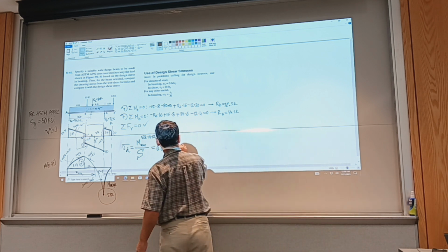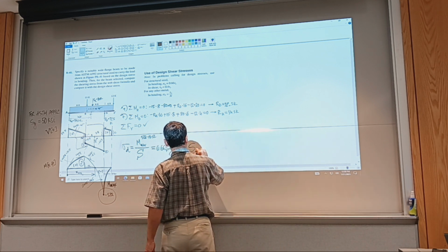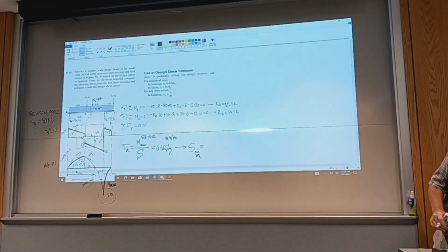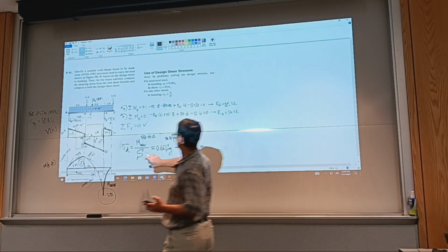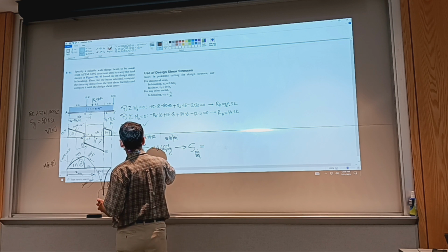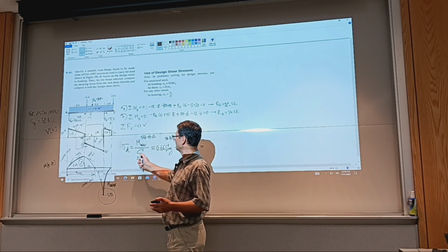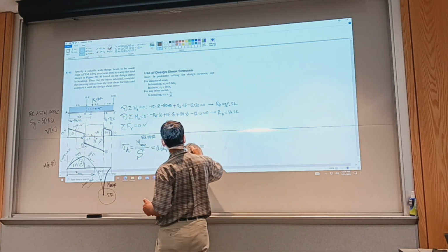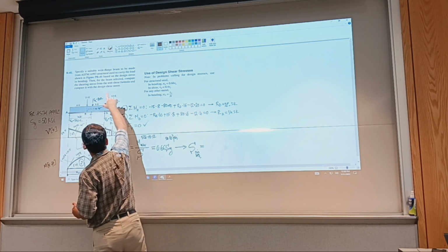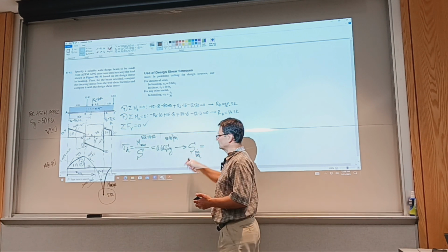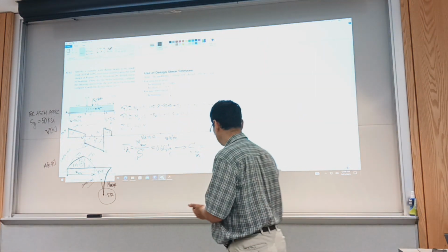And this allows us to calculate a minimum required area moment of inertia, or rather section modulus. The equation holds true seldomly for an available wide flange, so we need to find the minimum value and then find one that is the next size up, or at least suitable, if not bigger than the calculated S min requirement.